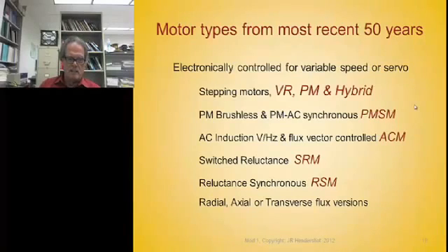But we come down here to these next two. These are reluctance machines. They're called salient pole machines, and there's only one magnetic circuit that's always in the stator, and the rotor becomes part of the magnetic circuit of the stator, but this part is mounted in bearings, so rotation results.